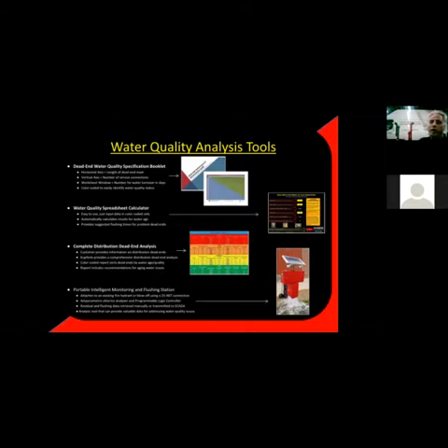So the majority of the dead ends, and this is what I find when I do this exercise for almost every city, 80 to 85% of them are green. We don't have to flush those lines in particular unless you get a call that my water looks bad, my water tastes bad, my water smells bad, whatever it might be. And you can go out and manually flush those lines.